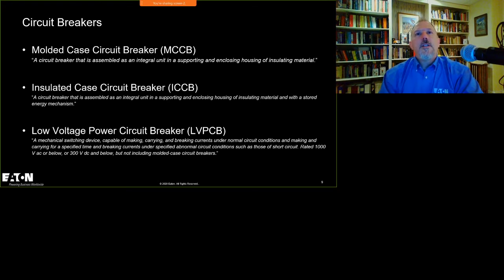So we have a question: does adding a molded case breaker inside a pad-mounted distribution transformer constitute refurbishment or modification and void the UL listing? All right, Nathan. If you add a molded case circuit breaker into a piece of equipment, you will probably need to get a field evaluation if it's not listed for that application.